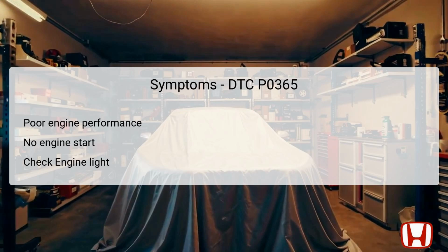When dealing with DTC P0365, several symptoms may indicate the presence of the issue. Drivers may notice poor engine performance, which could manifest as rough idling, reduced power, or stalling. Additionally, the vehicle may exhibit difficulty starting. In some instances, the check engine light will illuminate on the dashboard, alerting the driver to a potential problem requiring attention. These symptoms can signify that the camshaft timing is not being controlled properly due to a lack of signal from CMP sensor B, leading to serious engine operational concerns if left unaddressed.